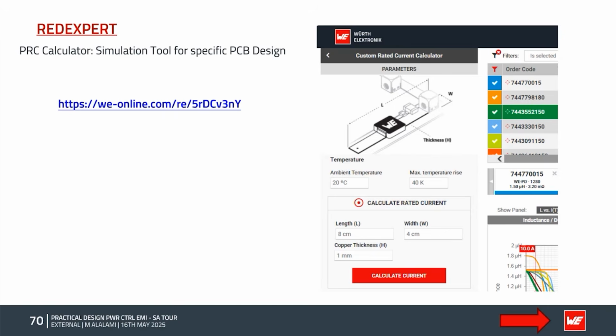So if the performance rated current in the datasheet says 5 amps based on a class C board, which is 3 ounce copper, and now you enter that you're only using 1 ounce copper and a much smaller track than a class C board, then okay, that current is no longer going to be 5 amps, it's going to be 3.7 amps, for example, just to give you an idea. So you can basically calculate your rated current yourself using this tool.